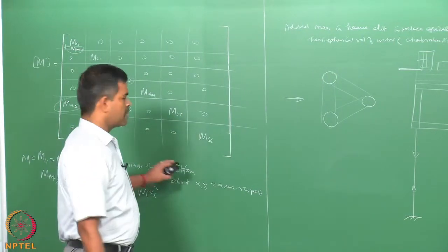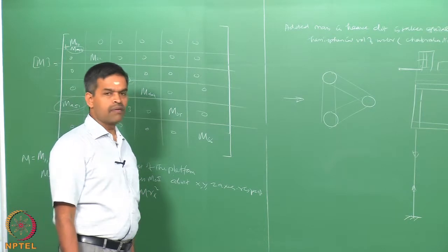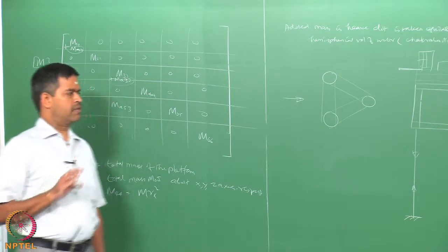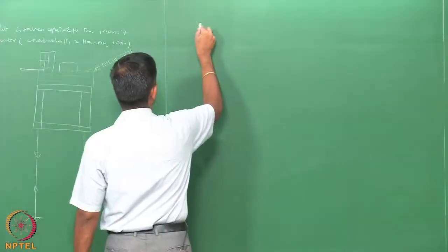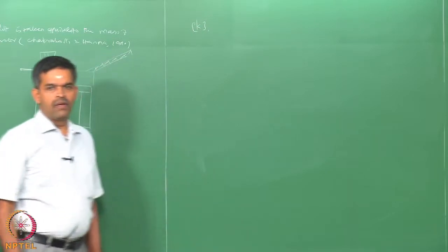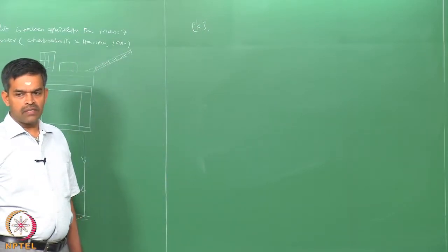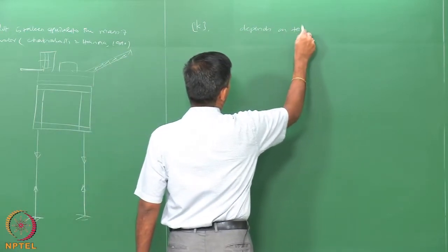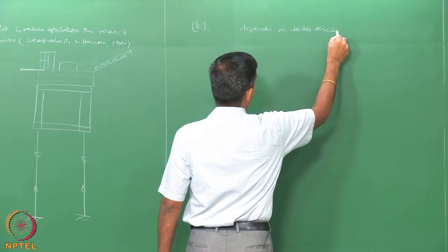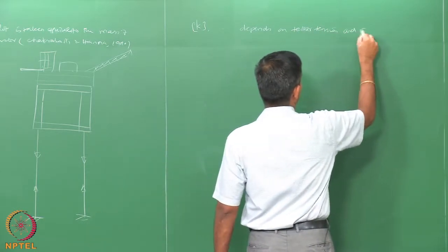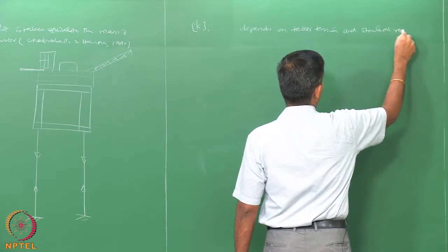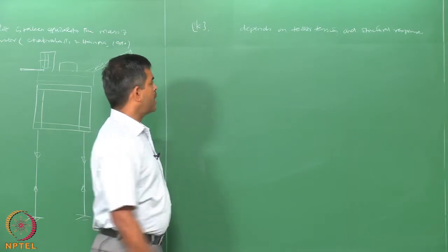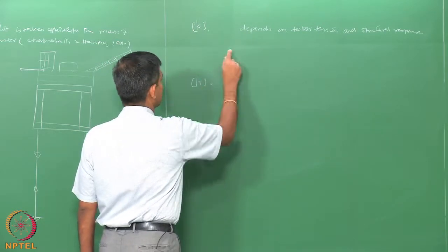Now, interestingly, in this particular equation or the study, contribution of added mass is taken up to the MSL, which is included along the force vector. Okay. The stiffness matrix now, which is indicated as K, depends on tether tension and is response dependent as well, depends on tether tension and structural response. Okay. So, for a triangular TLP, the stiffness matrix